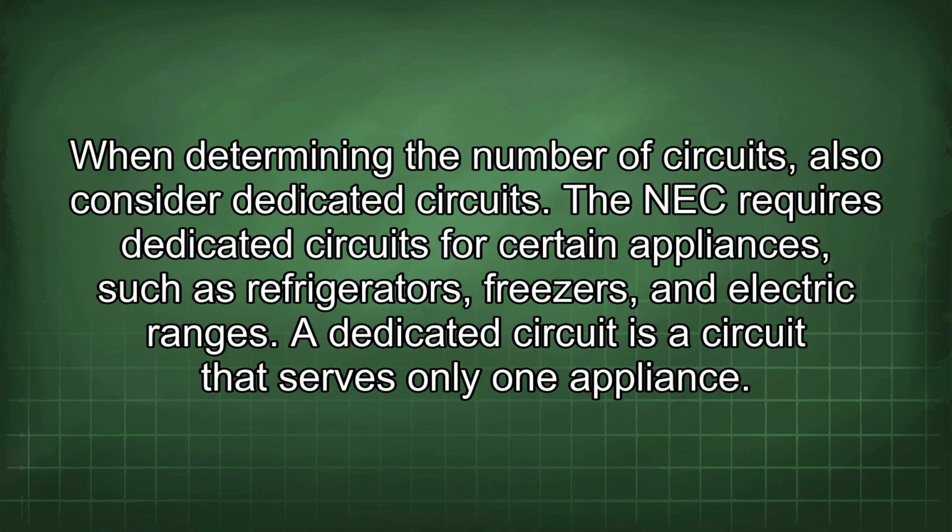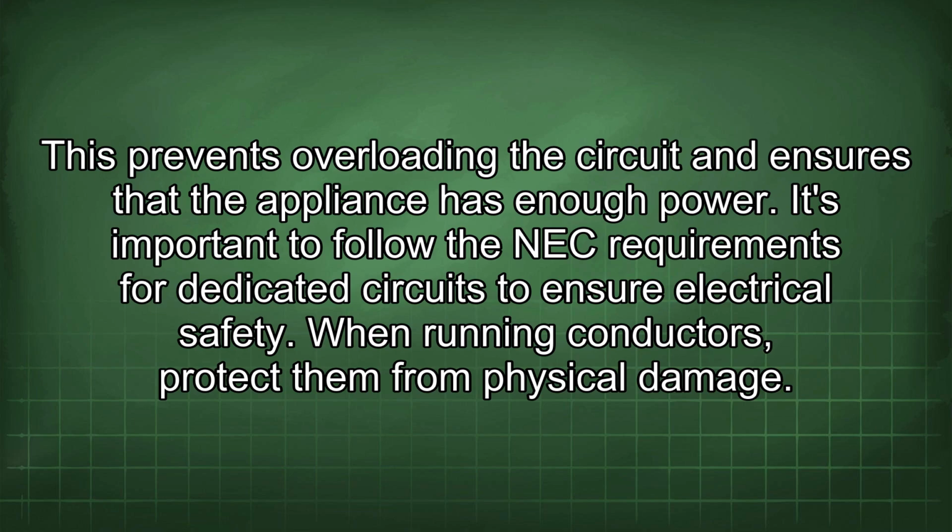When determining the number of circuits, also consider dedicated circuits. The NEC requires dedicated circuits for certain appliances, such as refrigerators, freezers, and electric ranges. A dedicated circuit is a circuit that serves only one appliance. This prevents overloading the circuit and ensures that the appliance has enough power. It's important to follow the NEC requirements for dedicated circuits to ensure electrical safety.